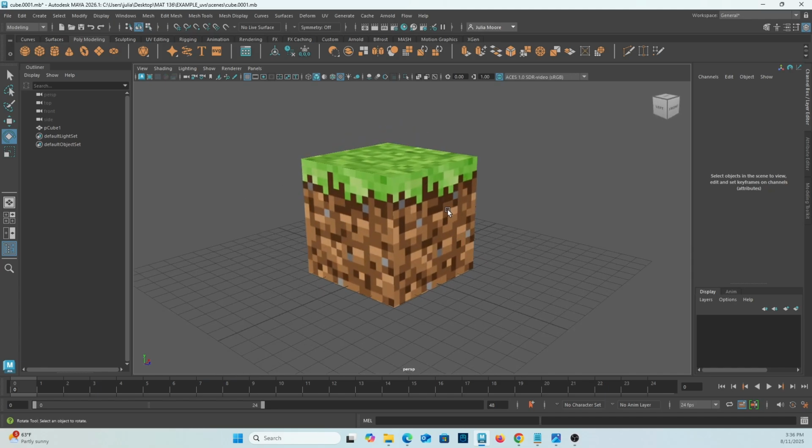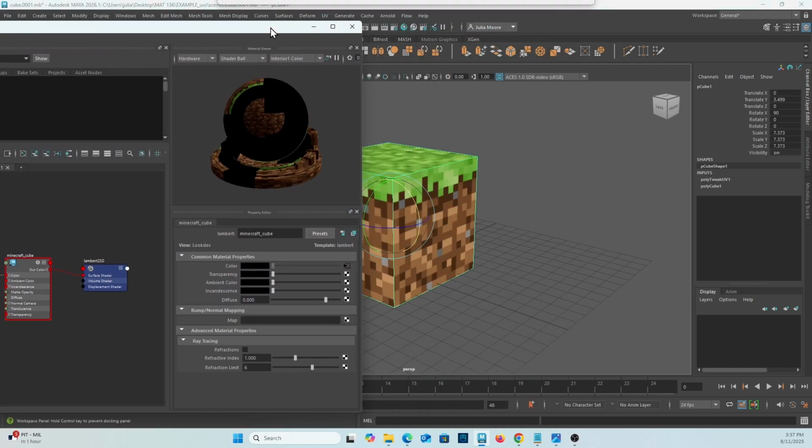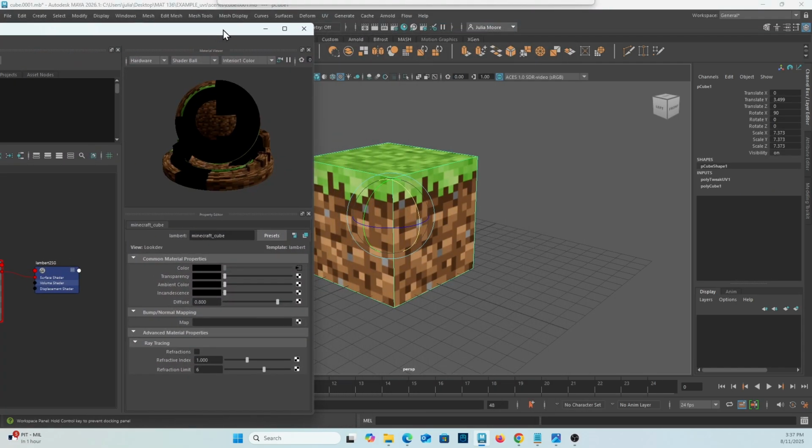So what did we do? Well, we first opened up the UV editor and we unwrapped our 3D object. We created a 2D UV map. We then took that UV map into Photoshop where we applied the texture. We exported that image and we brought it back to Maya where we connected it to a shader and applied it back to our 3D object. So that is how you texture in Maya, by UV mapping, UV unwrapping, and UV mapping it again. We'll get further into it in our project.